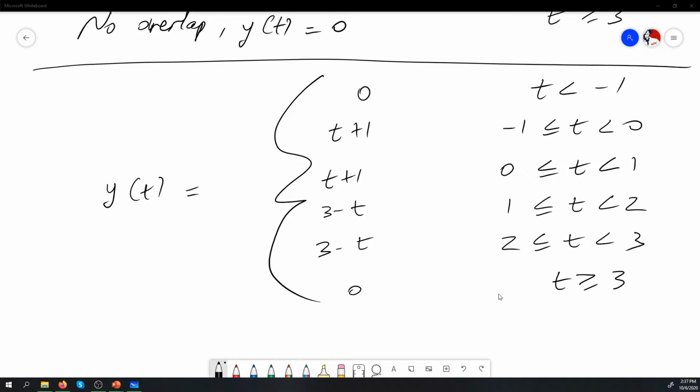And this is just to show you an illustration that if you shift your h(t) signal, all the outputs of the convolution also shift accordingly as well. And that shift is determined by how many units the h(t) signal was shifted by. So you don't have to reperform an entire convolution if the h(t) signal has been shifted by a certain amount of units and you have already performed the convolution for the same two signals, just in different positions.